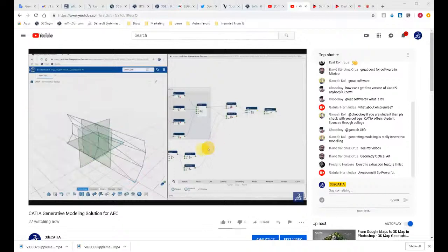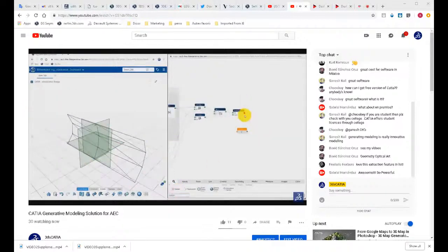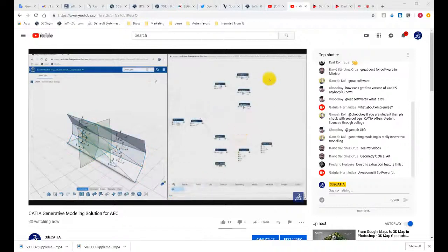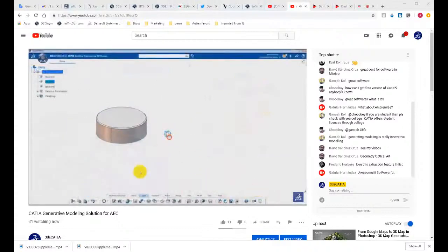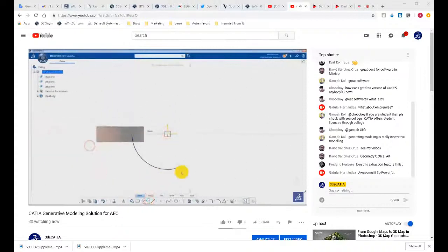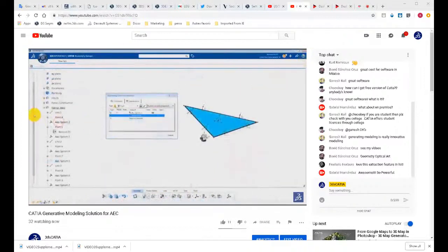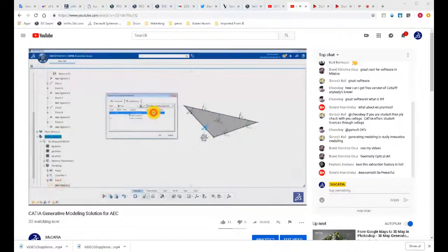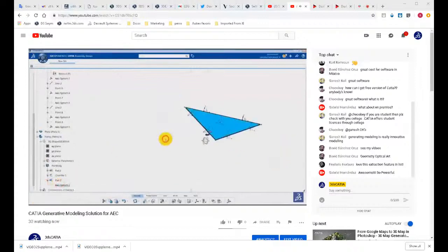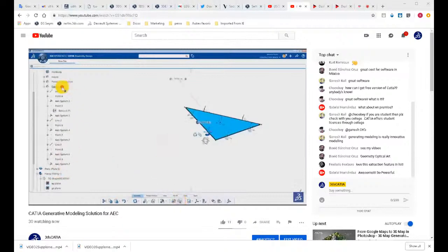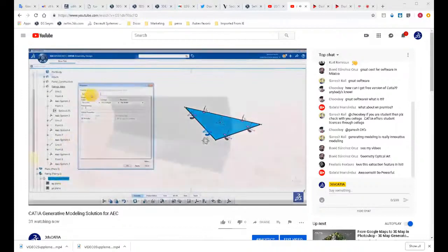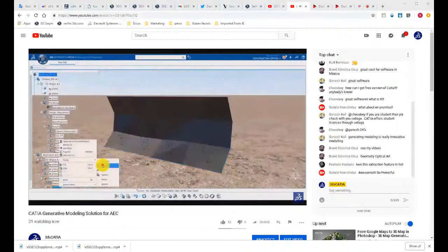So through list manipulation, we come up with the triangularization pattern. We can control the polylines and change them back and forth, change the orientation back and forth. We have axis systems that will anchor our engineering templates. And then in CATIA, the Rich client, we're going to show you how to model an engineering template from scratch. This is a fixation component that's going to be used to assemble our panels. You see how we create that engineering constraint within our model that positioned our panel, and now we're going to do an assembly pattern within that panel for all of our fixings that are common across all of our panels.